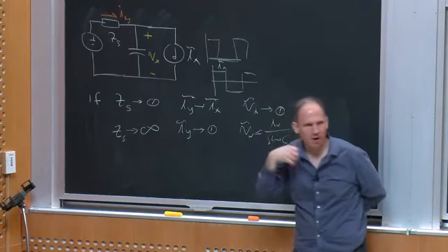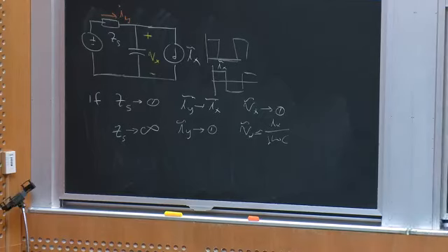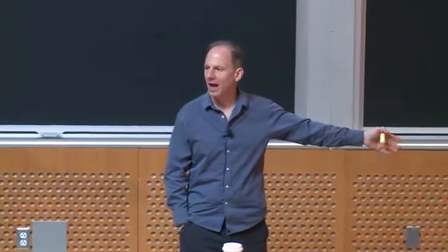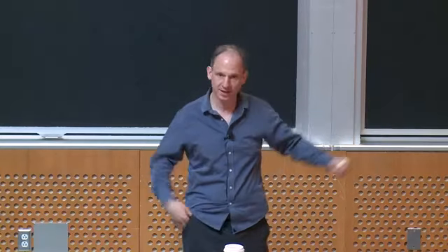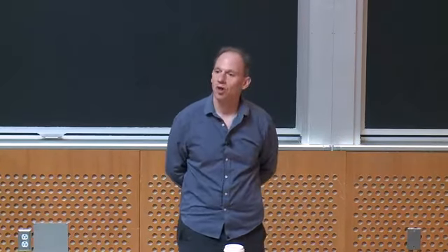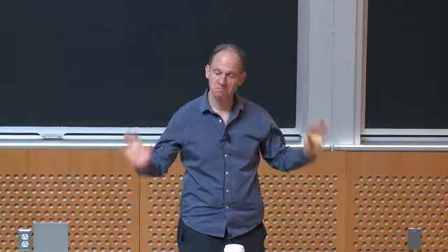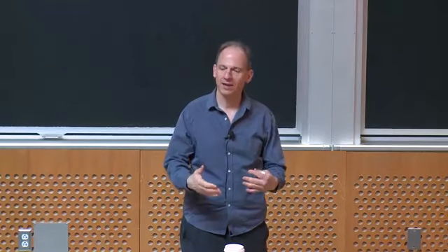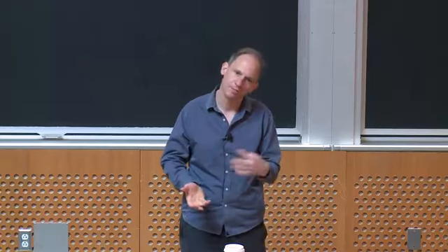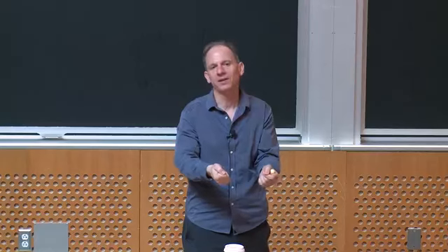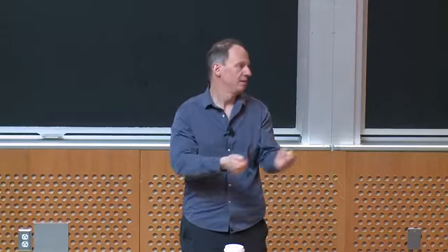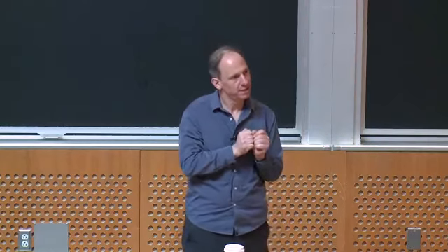And that's a problem because here's the way EMI works. If I want to go sell a power supply, a commercial power supply that I'm going to plug into the wall, I have to go test it and make it meet standards, okay? And then I don't do anything. I just take that result and I put it in a desk drawer. And as long as nobody complains, great. But if somebody comes back and says, oh, you're emitting too much EMI, then I've got to produce this test result and we've got to come to some agreement. Or they've got to be able to ascertain, did my power supply pass the test or not?